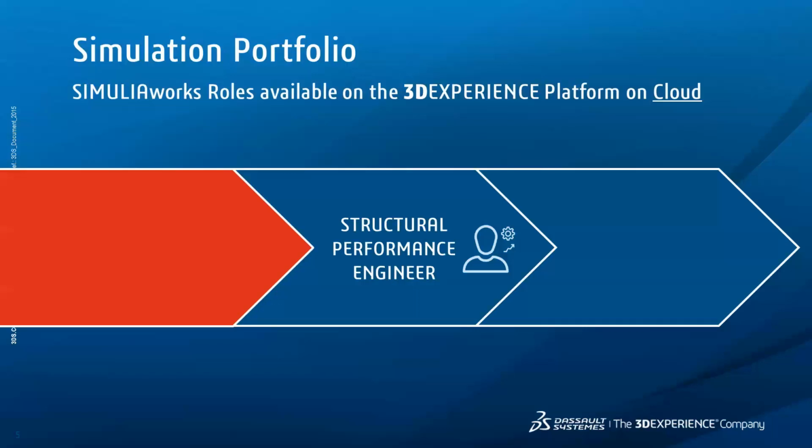Extended on that, we have structural mechanics engineer. It has the same functionality as structural performance engineer, but it has more procedure types and also brings the Abaqus explicit solver to the table for those particularly troublesome problems. This is particularly useful when dealing with crushing, rapidly changing contact interactions, and drop test scenarios. Both these roles have access to expert-level meshing apps, an enhanced element library, including hexes, and the ability to accurately model material behavior, even into damage.